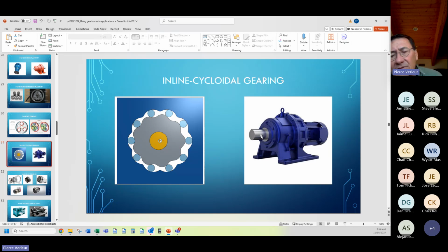Well, satellites with 18-meter dishes, unless they're under a radome, which is a big dome that prevents wind from affecting the dish, and the big ones typically are not, the wind's going to affect them and try to move them. That's that external force that I'm talking about on this output shaft. That'll cause deflection of the whole dish, and the dish will get off target. So that type of stiffness is very important in precision applications.